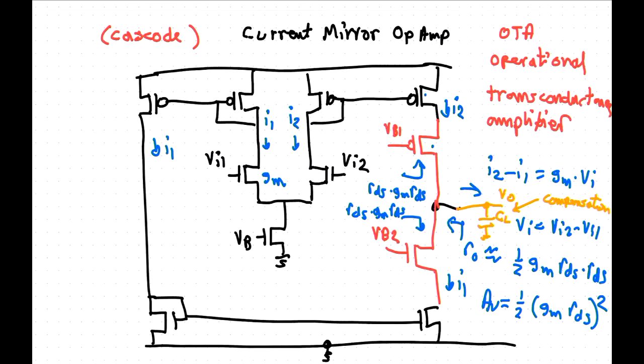If you put in a cascode underneath here, it doesn't matter, because it's still the same impedance level in that node. I thought we cascode to raise the impedance. You cascode at the output.